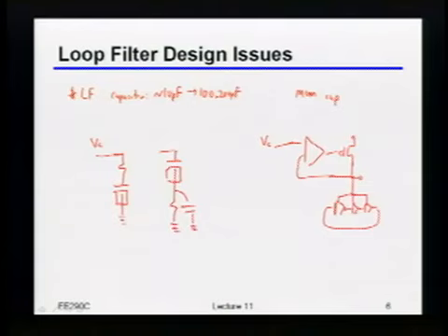So if I've got a bottom plate cap down there that's in parallel with the resistance, remember the resistance was there in the first place because I needed a zero. So if I now have an extra pole there, I could basically completely screw up my stability, okay? So indeed, you typically will end up building it so that it looks like this, okay? So at least if you have an NMOS, in fact, even usually with a PMOS with caps, you'll usually build it like this.